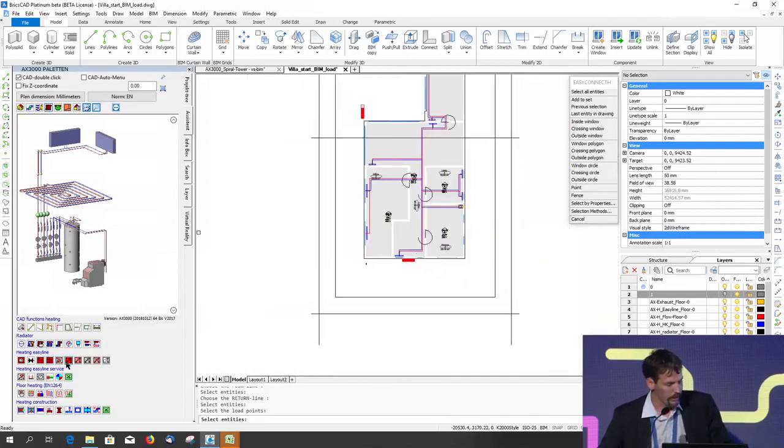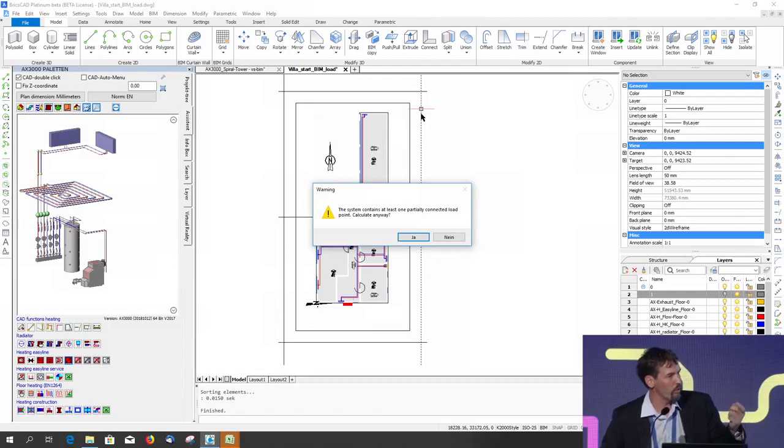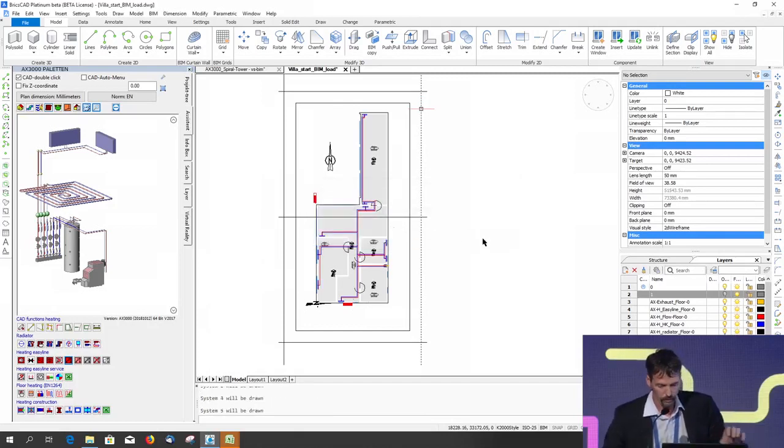And so at the end, I start the calculation process. I select my windows, or with the window my system. The calculation is started. The load at every position is calculated. Because of the starting point, the software knows that the medium is at the moment water. I have a density, a velocity, a heat capacity, so I get a pipe dimension, and at the end, I get a mass list and a physically correct calculation.